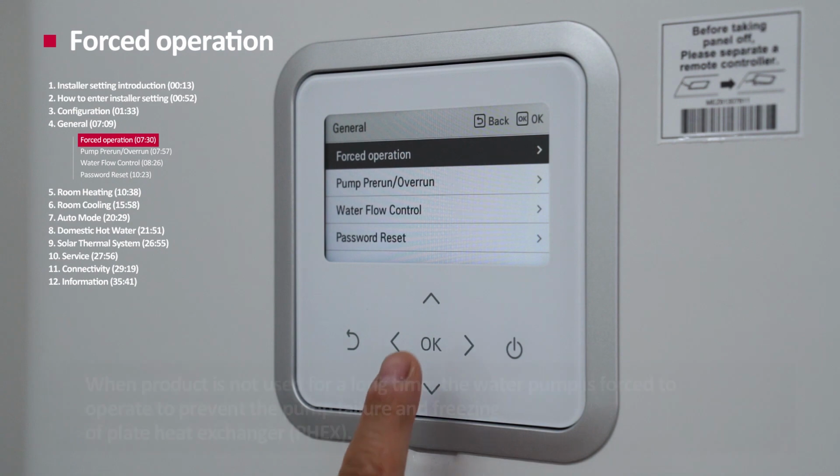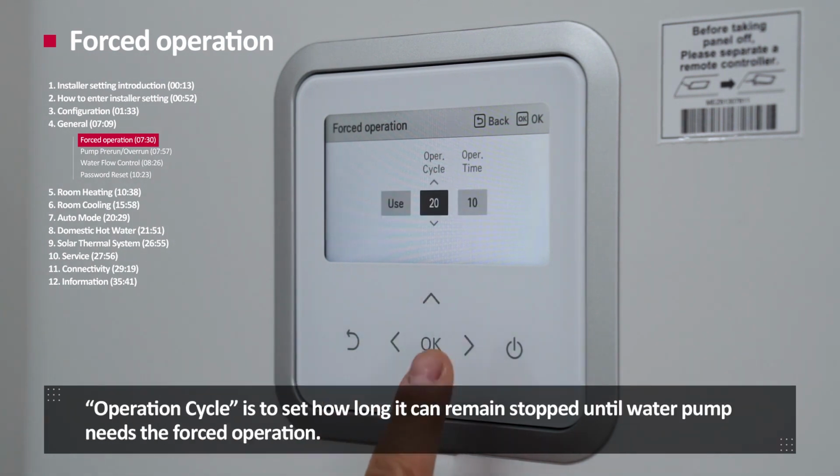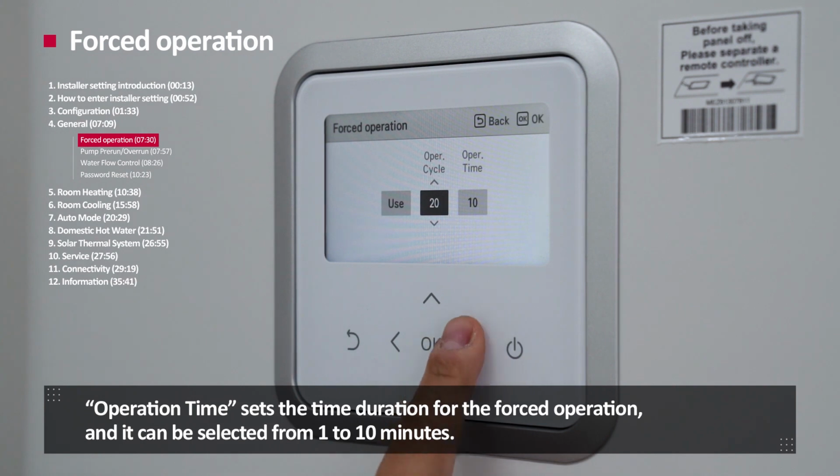Forced operation. When product is not used for a long time, the pump is forced to operate to prevent the pump failure and freezing of plate heat exchanger. Operation cycle is to set how long it can be remained stopped until water pump needs the forced operation. Operation time sets the time duration for the forced operation, and it can be selected from 1 to 10 minutes.